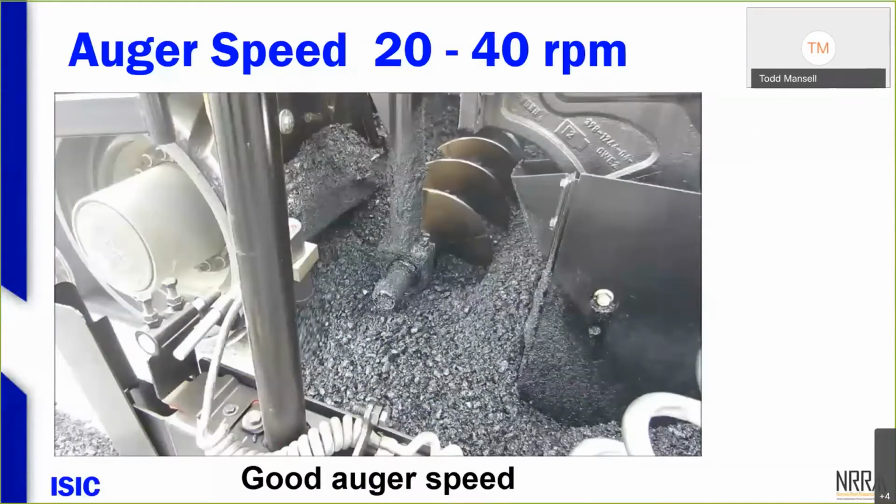Okay, thank you. So those two video clips were just showing fast auger speed, and now showing on here 20 to 40 RPMs, or about 2 seconds per revolution. Again, it's just a goal, but with a paver-mounted thermal profile, you see different patterns. We can go back and look at our auger speed. If we get wispy images behind the paver, it might indicate on-off auger movement or just high auger speed or slow auger speed, which translate to material segregation and thermal segregation.